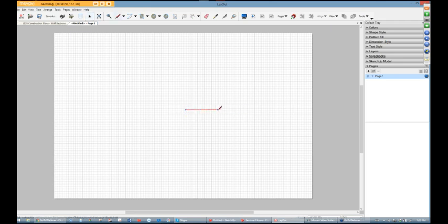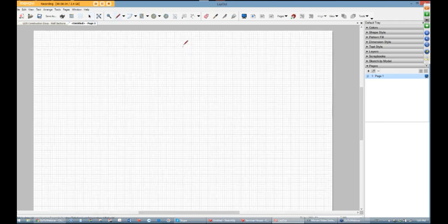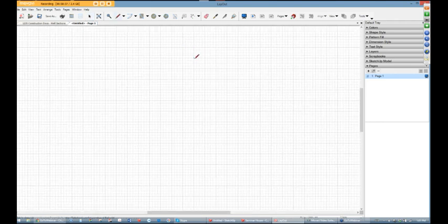So right now, let's put this on grid snap. So you have two kinds of snaps. You have an object snap, which is this guy here, this little magnet looking thing. And then you also have a grid snap. Right now it's off. So you have two different types. The grid snap will override an object snap. Object snap snaps to the drawing that you put in, and grid snap, as you might expect, snaps to the grid. So we'll put on grid snap right now because I want to be able to draw this title block. And you can see every one of these little spots in the grid it's going to snap to.